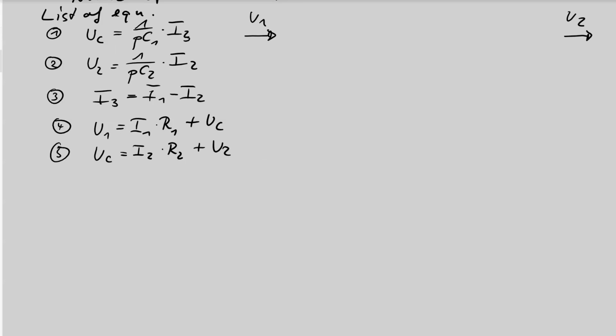And the strategy is now the same. First, count unknowns, calculate the number of equations, fill equations, and now we convert these equations into a signal block diagram, starting always from the output line, looking for an equation which contains U2, which we can solve to U2 and then draw it. If we go through the equations, the first equation is not usable, second equation is possible, third has no U2, cannot be used, fourth has no U2, cannot be used, but you see equation number 5 also can be used to get a picture for U2.